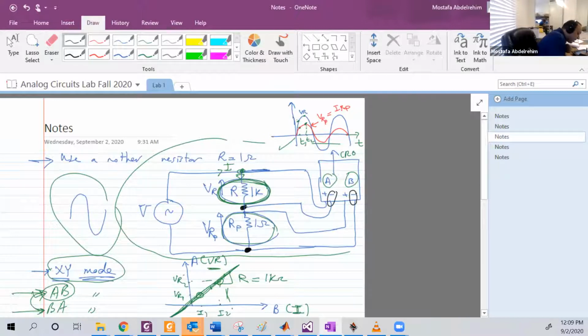Then you will have a ground here and a ground here. So you have shorted the 1 ohm resistor. So you will read just zeros, something like this, just 0 on channel 2 or channel B. So this is not actually a valid connection if we're going to make it on a real oscilloscope. Of course, we want to be very close to what we're going to see in the real world. In the real world, the oscilloscope has a common ground, only 1 ground.